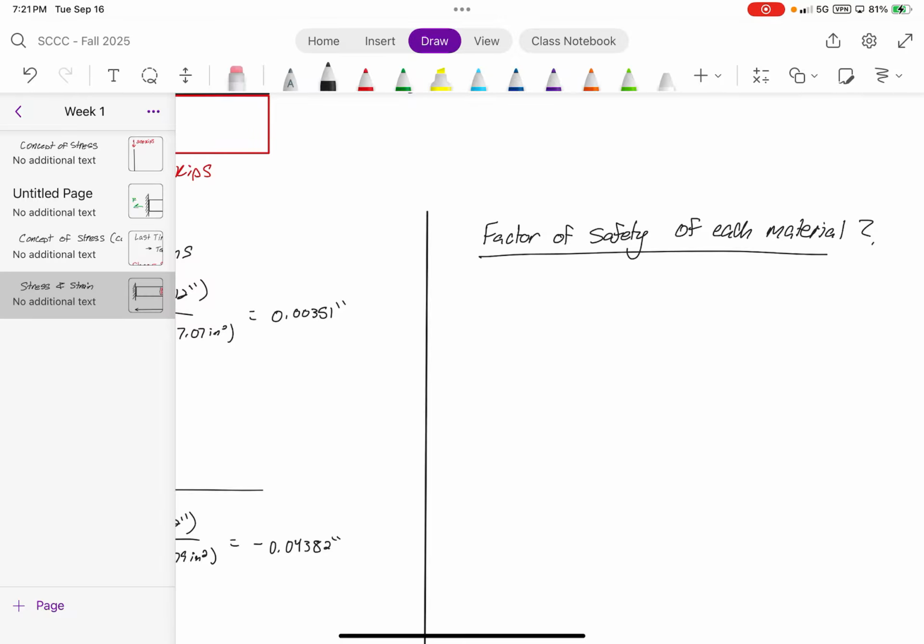You guys learned a little bit about what the factor of safety is from your previous exit activities, right? What did you guys do with the factor of safety? You just multiplied it by whatever the force was, and then you checked it against the capacity. The true definition of what the factor of safety is, we call it FOS, is a ratio of the capacity over the demand.